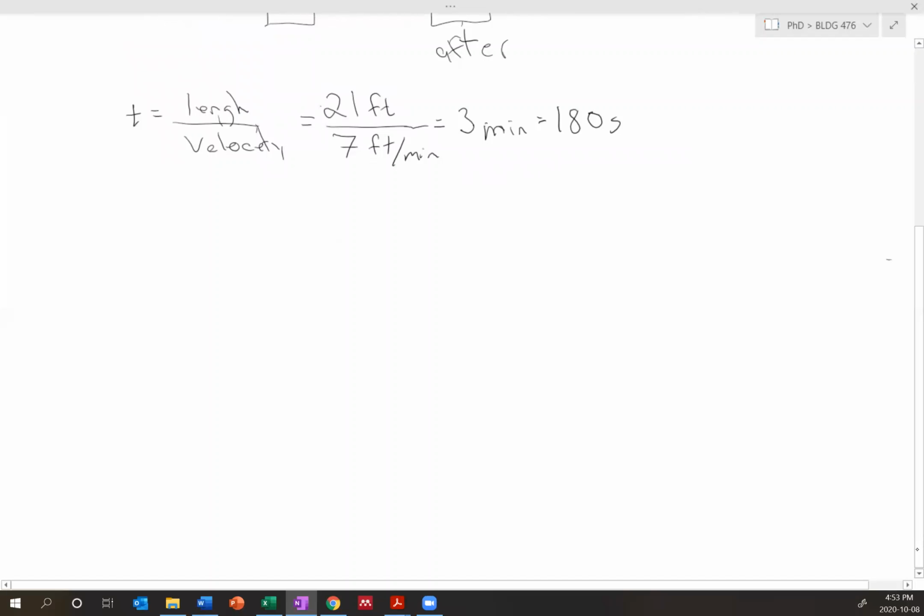The next step is to calculate the Biot number. So Bi is equal to H R naught over K, or rather R. Remembering that this is actually the characteristic length, but we've done it enough for cylinders now that we're used to the fact that it's just R, because all the pi's and everything else cancel out.